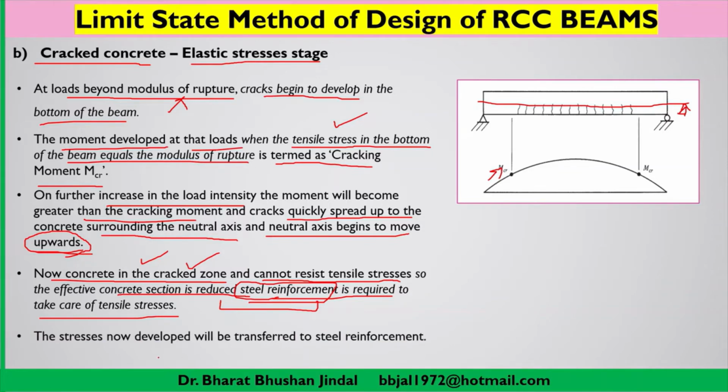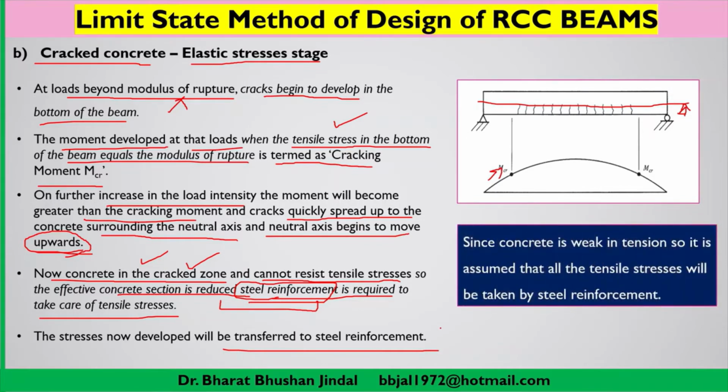So the stresses now developed will be transferred to the steel. Beyond this, the steel will start taking the tensile stresses. Here we can conclude that since concrete is weak in tension, it is assumed that all the tensile stresses will be taken care of by the steel reinforcement.